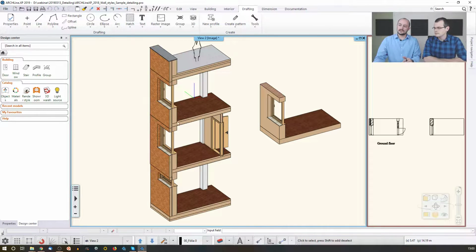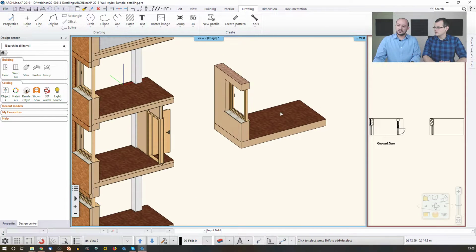So for this reason, I have created what I usually call a conceptual model, a simplified one. Many times I also start like this. I have an idea, but I don't know exactly, and I don't want to worry about what sort of structure I would like to use at the end. I just literally would like to sketch things as fast as possible. So I'm using one-layered walls, one-layered slabs and things like that. And when I do that, they tend to connect like this.